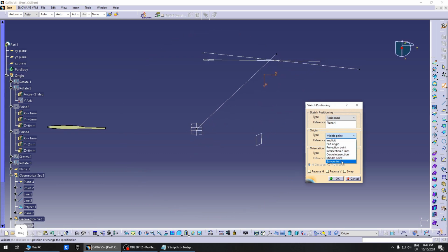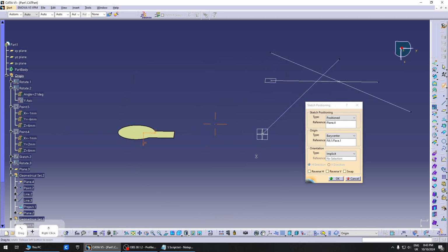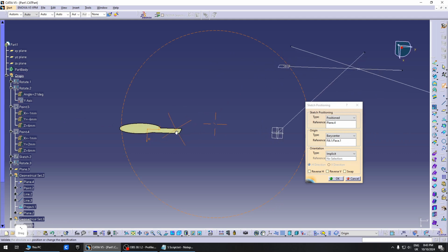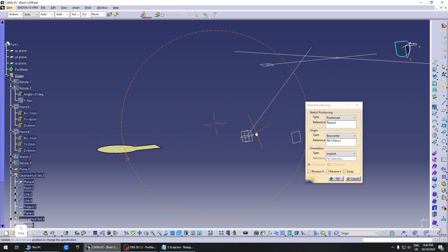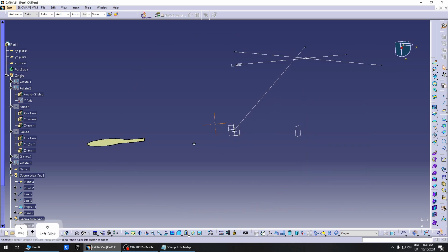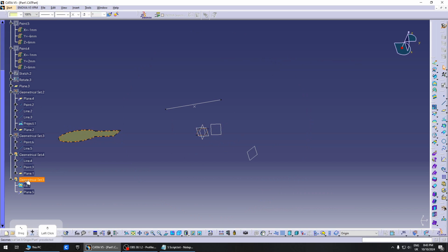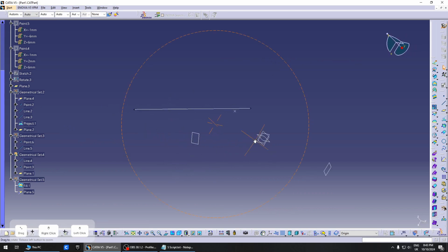Right? The weird one is the very center. This one will actually require a surface as an input, and it will automatically calculate the geometrical center of that surface and project that onto your reference plane as before. Okay, we did not talk about the curve intersection one. This one is a bit different, not much, but it is slightly more interesting.